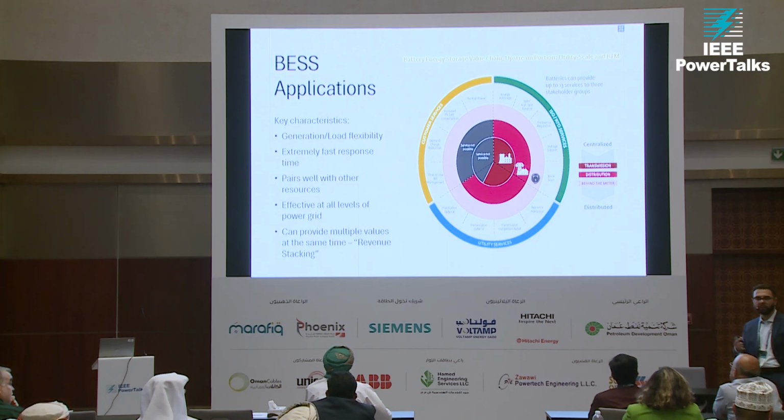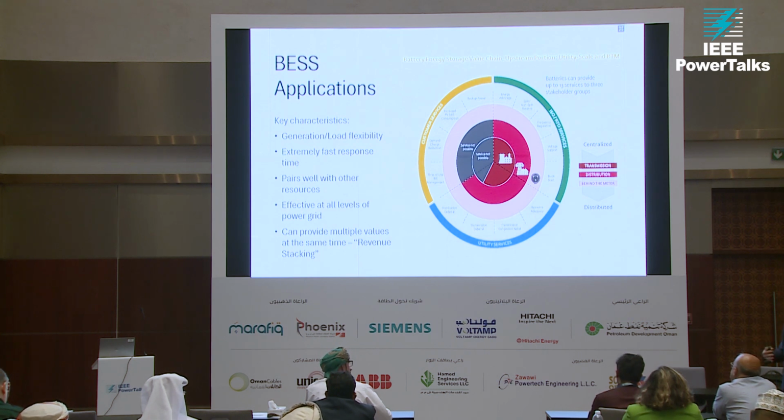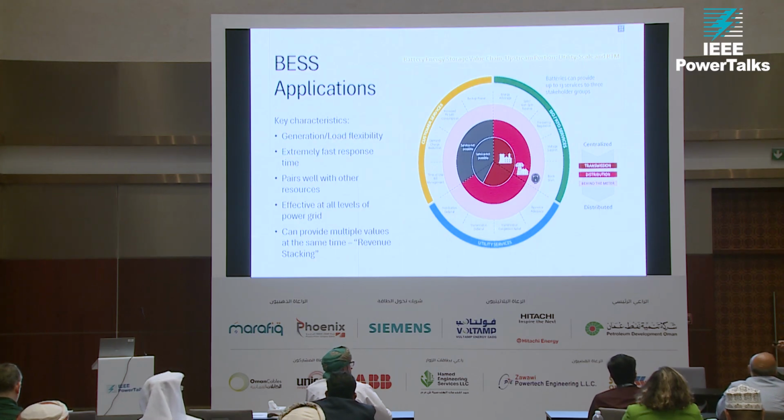Because if you have a congestion in one area, but that's only seasonal, or only time of use congestion, then you use those batteries to relieve the system, so you don't have to build and upgrade these systems. And this is a really very interesting application. The first project in New York City, in 2015-ish, 2016, was really driven by distribution deferral.